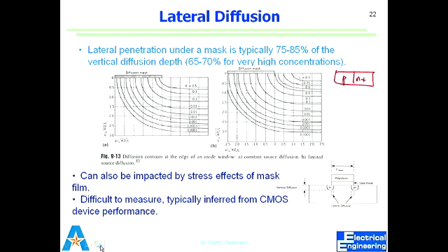But the difference is that in ion implantation we can have the peak of the distribution at some depth, which we don't necessarily need if we are doing a source and drain implantation, because we want that peak to be on the surface. Then it behaves the same way as diffusion. The difference is only how we got the dopants into the substrate. In one case, we have to heat it to high temperature. In another case, we can do it essentially at room temperature, just bombard ions.